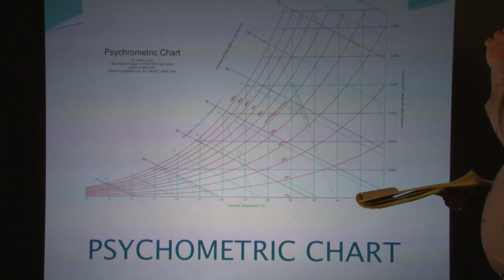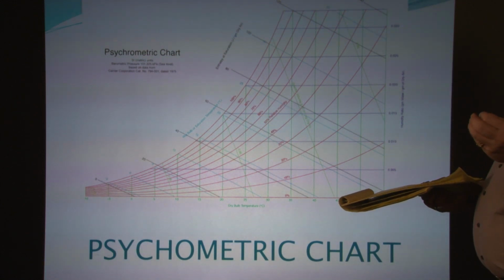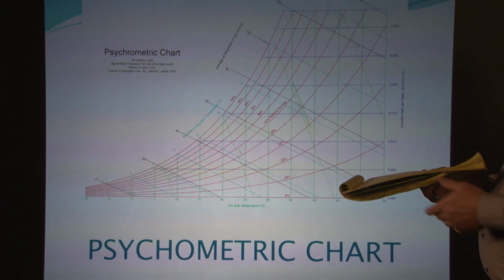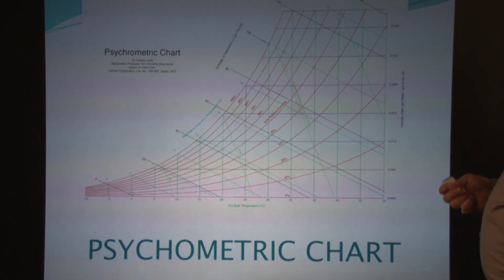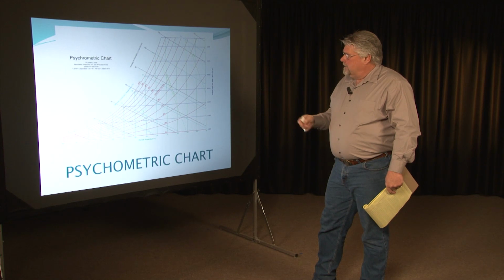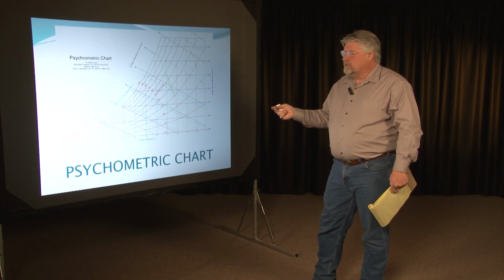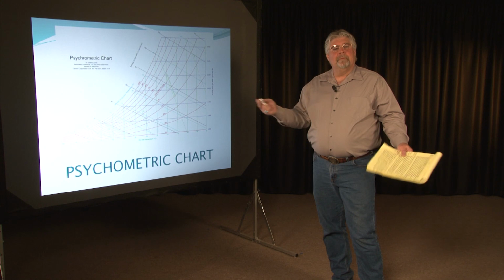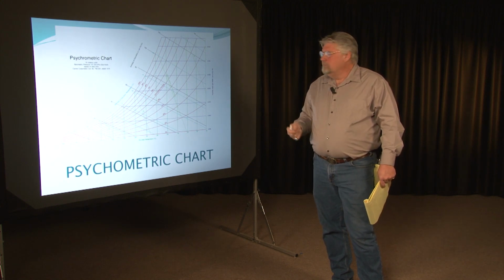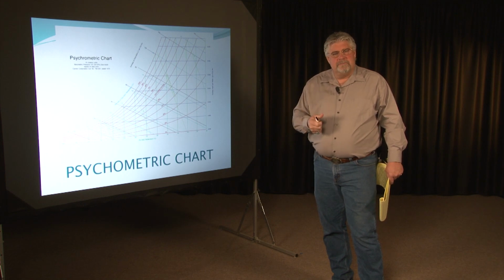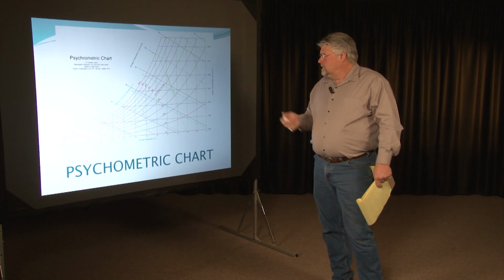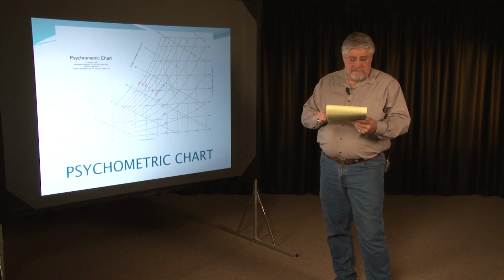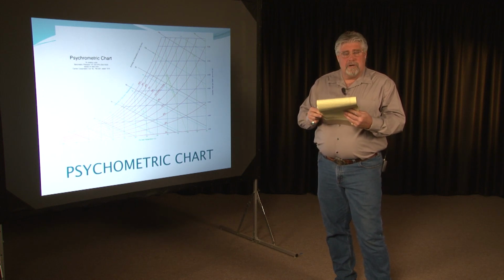So this chart basically covers all the bases as far as figuring out what percentages and temperatures affect what, as we've just talked about. Wet bulb, dry bulb, relative humidity, dew point. All of these factors combined all have a reading that is taken into consideration by the air conditioning engineers who design systems for a typical building, depending upon these graphical measurements and percentages. That's how they design the system for commercial buildings or industrial buildings. So it's a big part. Not that you have to know that in particular, but this is just how it's done. This is the method used, the psychrometric chart.